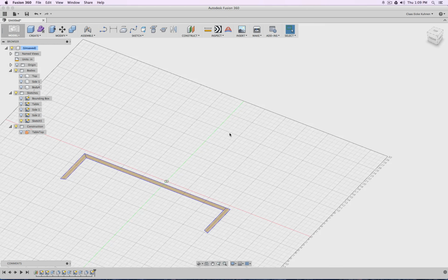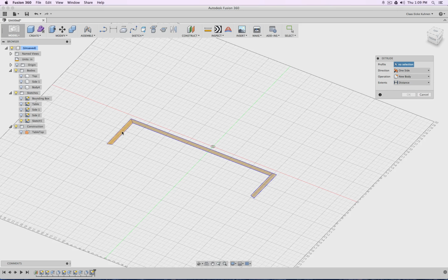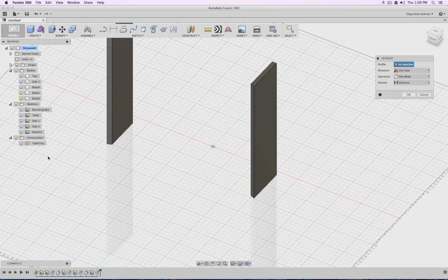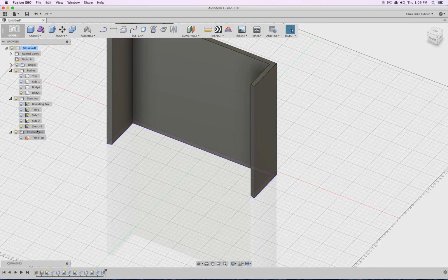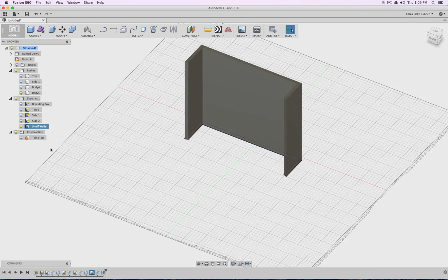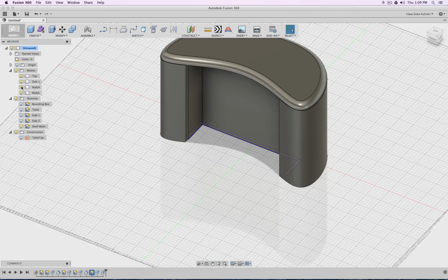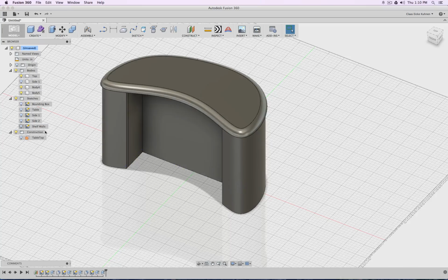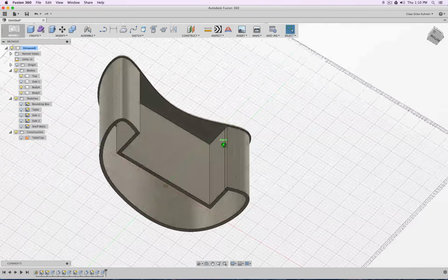And then I could say stop sketch. And then do extrude, new body, and let's say repeat, there, okay, and this, for example, maybe we call shelf walls. And how to put in, for example, a shelf, I skip, since we did this in a previous step. But this way you can see how neatly everything can quickly stick together.